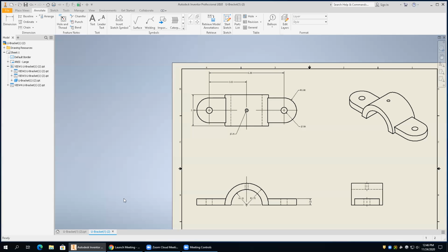All right, great. If you want to save this for yourself, you can, feel free. We're going to start a new drawing and we're going to do this thing called a revolve. So we're going to draw a path curve, and we're going to revolve it around an axis. So it's going to sweep it around, and it's going to generate a piece for us. Then we're going to do a mirror on that part, and then we're going to put a pattern in there in an array and cut that out.